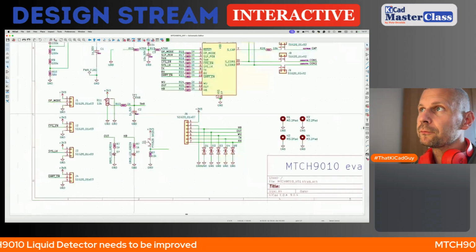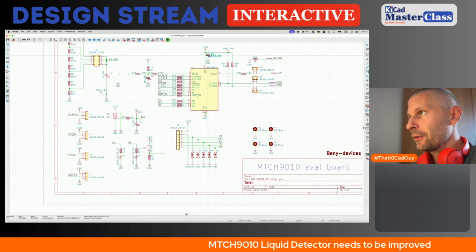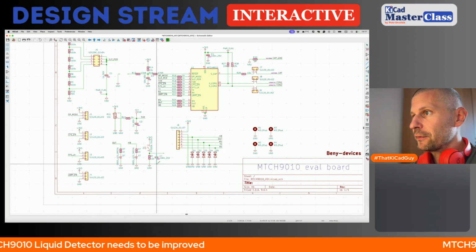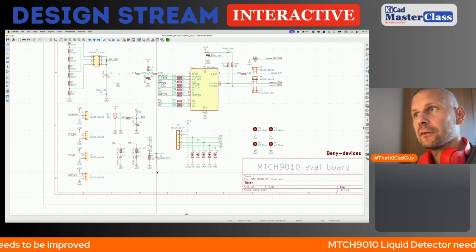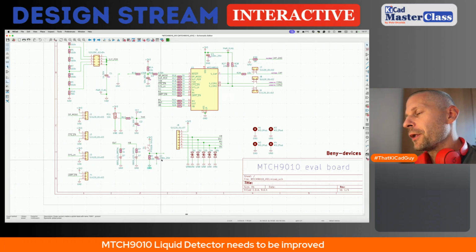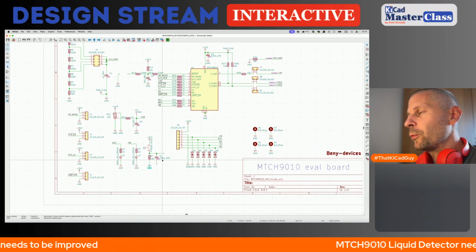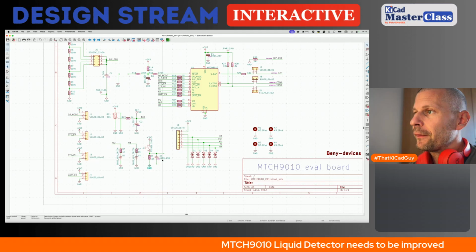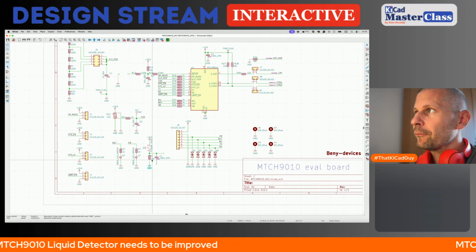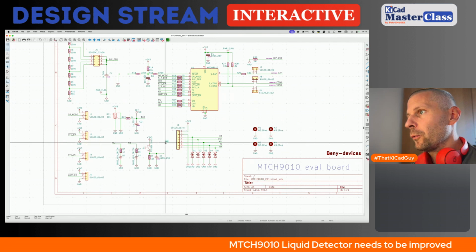I will use 10K. It means we can use 100 nanofarad because the time constant will be about 1 millisecond. No, 0.1 millisecond. No, 100 times 10K times 10 to minus 9 is minus 7, 10 milliseconds, I think. Okay, this will work. Wake up.